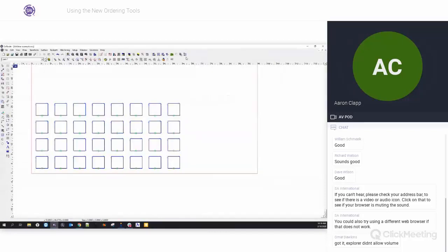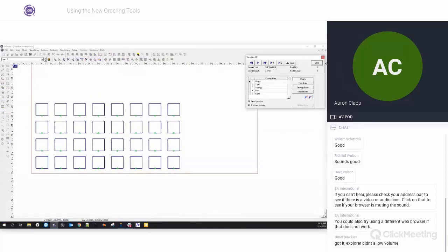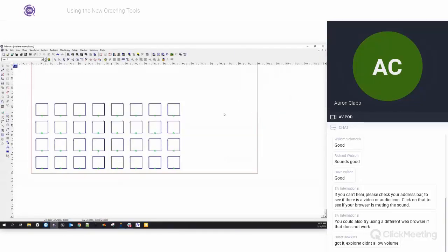So if you guys were doing a manual toolpath with the set toolpath order, you'd actually have the same thing happen. You'd want to make sure that the object is at the top and that none of the boxes are checked because now it knows that it has to use the manual ordering or the order by line. So really simple. We can do this and we can do all kinds of stuff with this. So I can have it go something like this.